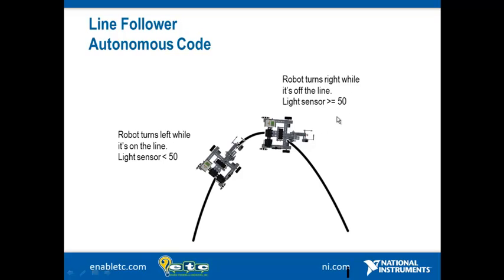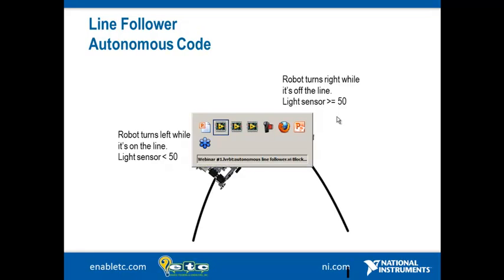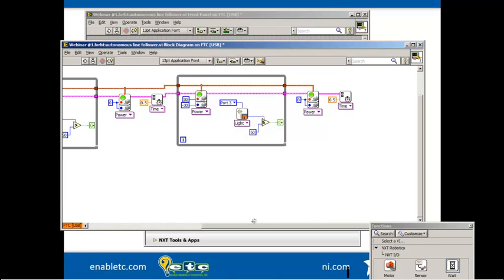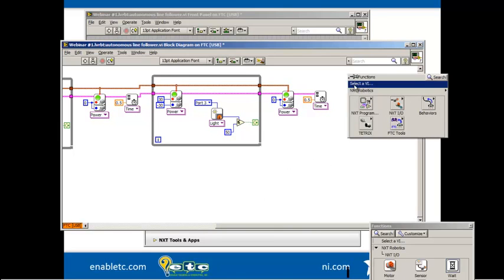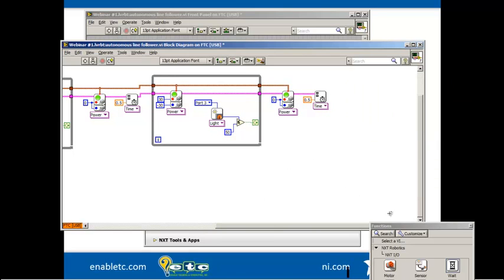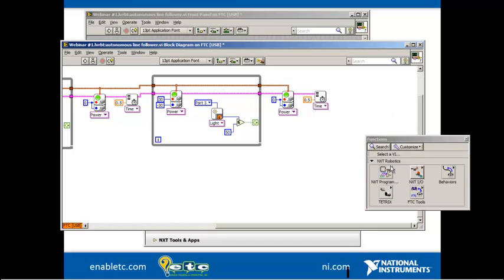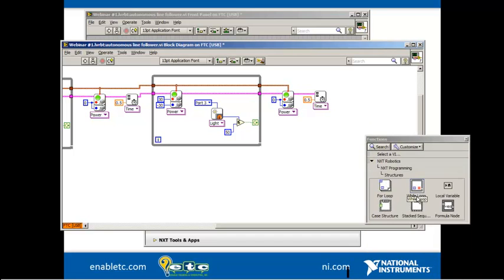We've got all the pieces we need, and this is one of the great things about programming with a good approach and a clear algorithm. One of the things that can be done really easily in LabVIEW is to make duplicates and slight modifications of our code. So let's go back into our code. We're going to need to create another loop, so I'm going to right-click to bring up my functions palette, go to programming and structures, and create another while loop to the right of our code.